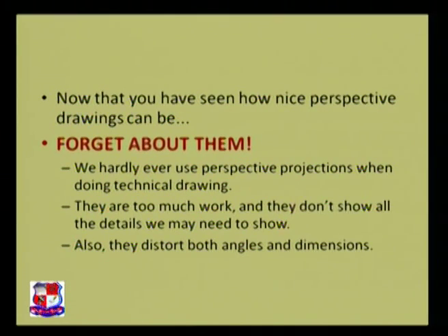One more thing, they are too much work and they don't show all the details that you may need to show in technical terms. Also, they distort both angles and dimensions. As you have seen in the projections, a far object will be smaller than a nearer object, so that's a disadvantage. So we can say that this kind of projection we can leave for the art class. It's not our cup of tea.